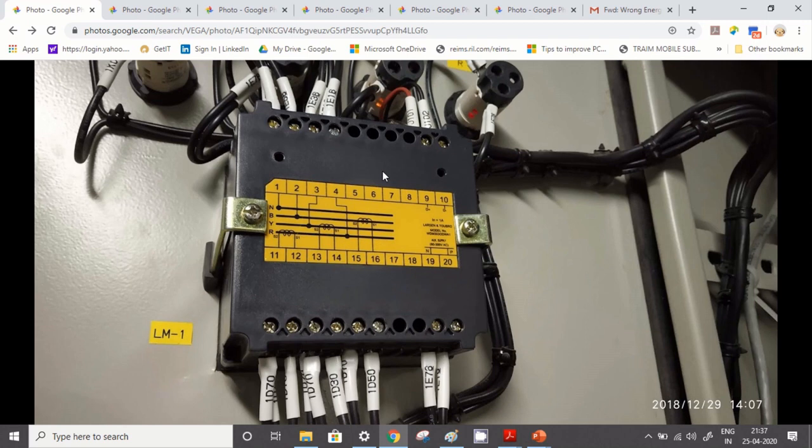After that, even if you are not getting the values, then you have to make sure that any one meter is correct. For example, if the EB meter is not running properly and your DG meter is healthy, and whenever the DG runs it shows the value and that reading is available in Everest, in that case you have to swap this meter between EB and DG. Normally at every site our EB availability is around 21 to 22 hours, so mostly the EB meter runs, and the chance of a problem in the EB meter is higher because it runs more, whereas the DG meter is idle almost 20 hours a day. So based on experience, we found that the DG meter is normally always healthy.